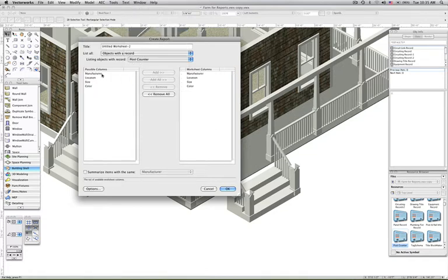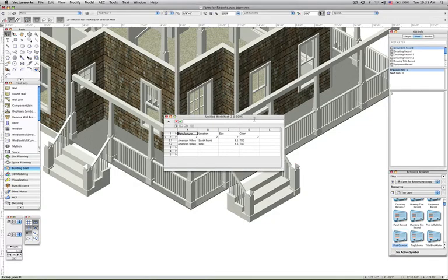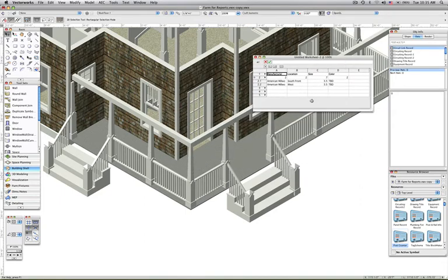Once the report is made, I can go back to my drawing and further populate the worksheet with additional data by entering the information into the data fields in the Object Info palette. As mentioned, this can be done at any time once the record format has been established. So now I'll go back and choose the post counter as the record I want to add additional data to.